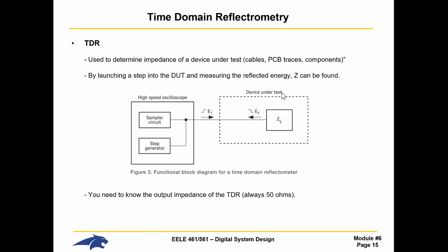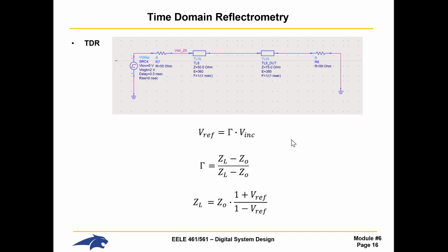With printed circuit board traces, you can figure out how well the manufacturer did on making a 50 ohm trace, or how badly you calculated the line width, or just flat out components. Sometimes you might have a receiver that's supposed to have a 50 ohm termination resistor, like on an FPGA, where you can program in termination resistors. You turn it on, blast something into it, and see if it reflects. What if you accidentally had it set to a 70 ohm resistor instead of 50? There are a million different things you can do with this. Actually, there's one thing you can do with this: measure impedance. But you can measure impedance on a million different things.